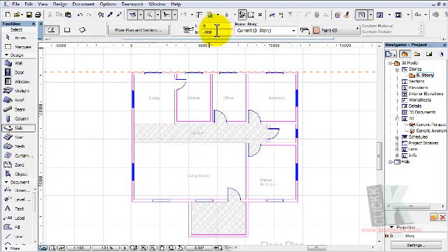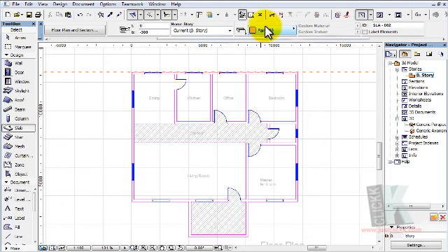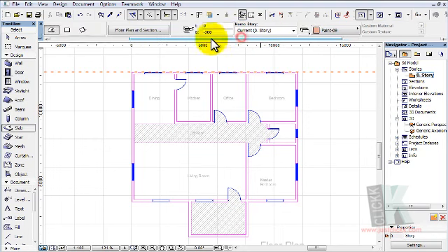So let's also look at the elevations here. You have the top elevation 0 by default, while the bottom is also minus 300 by default. What this simply means is that the 0 here is the earth surface, while the depth of the slab is minus 300. The color here doesn't really make sense, so let's use the default color.